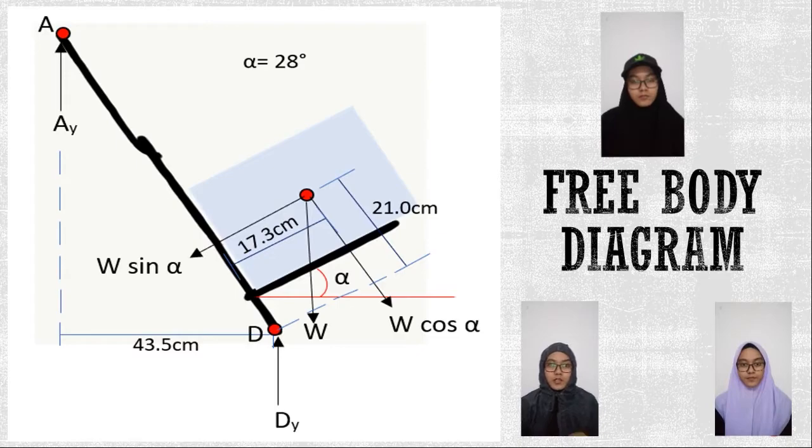First and foremost, we need to draw a free body diagram to analyze the system, which can be resolved in X and Y components. There is a vertical force applied at handle A and the reaction force at the wheels. Remember that there are assumptions to be made. The mass of the truck is small compared to the box, hence it is negligible. We calculate forces of the hand truck at rest, hence all the forces are in equilibrium. And remember, we have two wheels on this hand truck, hence the reaction force will be distributed evenly.